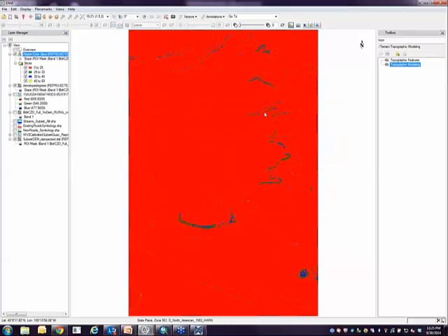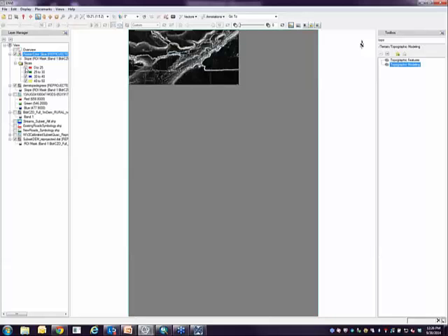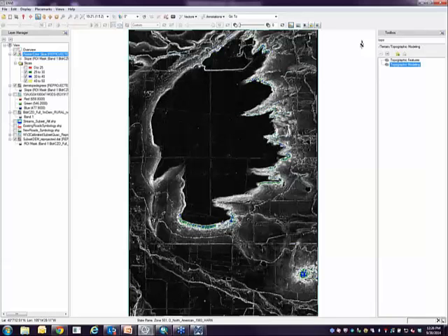So all the red, I don't really mind all these areas that are under 25-degree slope, because those are all going to be a 50-foot buffer according to my chart or less. So 50 foot's the minimum. I'm going to turn those off. And what I really care about are these areas that are blue and green and yellow.